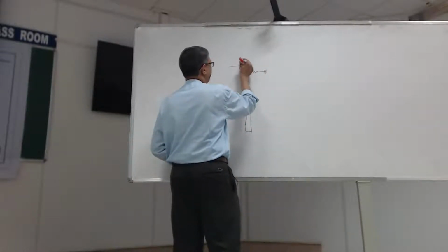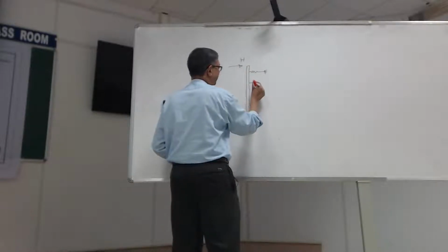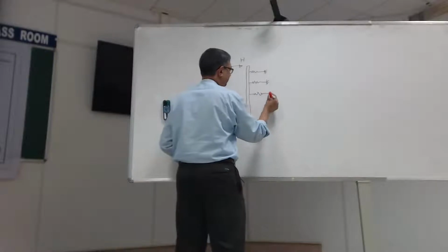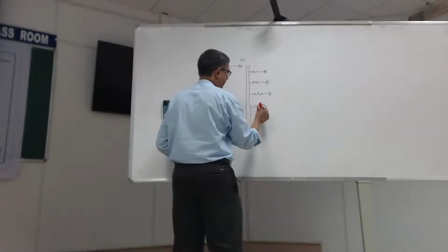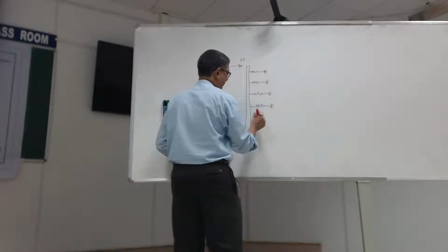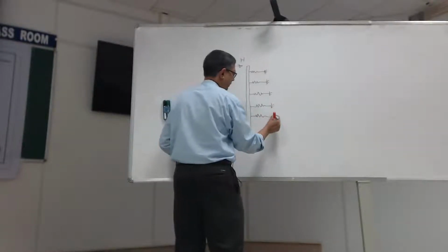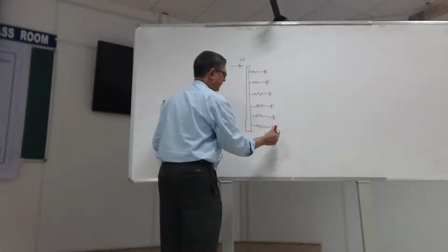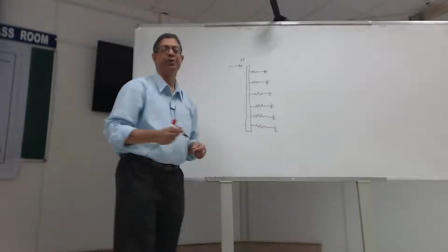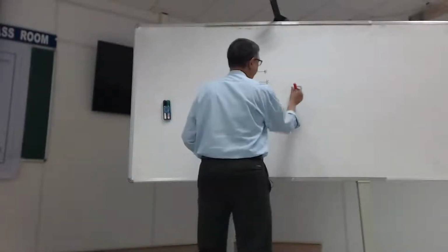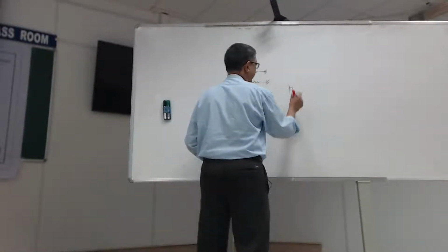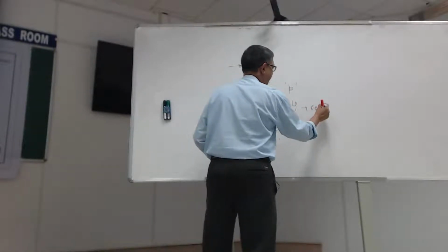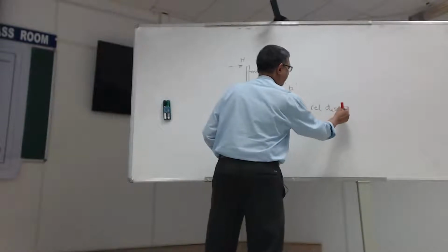It's used for horizontally loaded piles, originally developed. So the soil pressure acting on the pile is P, and Y is the relative displacement between the pile and the soil.